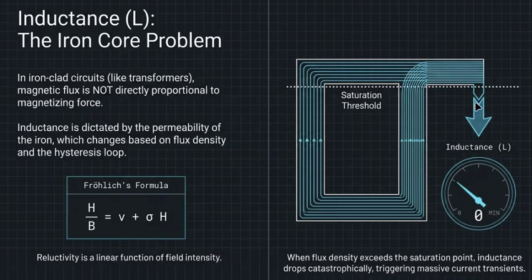How does that work? Well, if you completely erase all the residual magnetism in the iron core, and you perfectly time the closing of your switch to hit the exact peak of the incoming voltage wave, you get zero starting transient. The current just flows smoothly. Exactly. Smooth as silk. But we don't live in a perfect world. Not at all. Out on the grid, that iron core almost always has residual magnetism left over from the last time it was used. Like it remembers. Yeah, it really does. It's like someone holding a grudge.